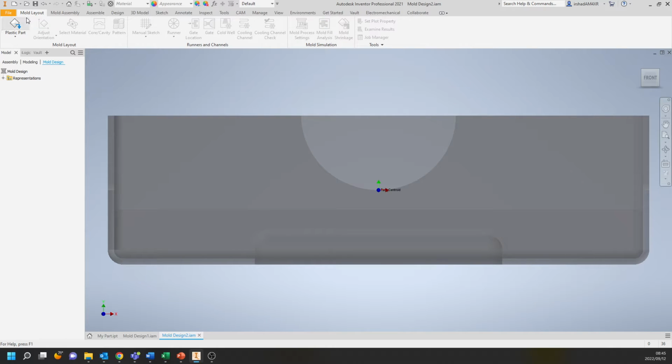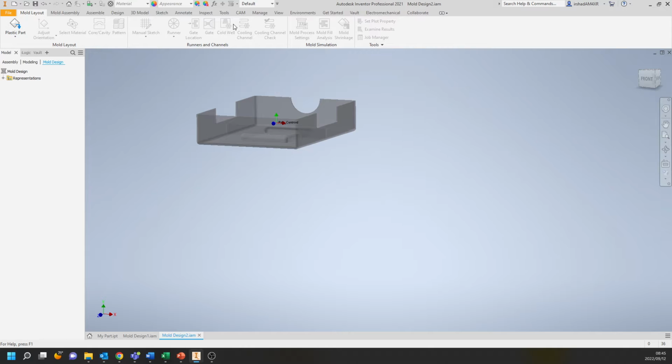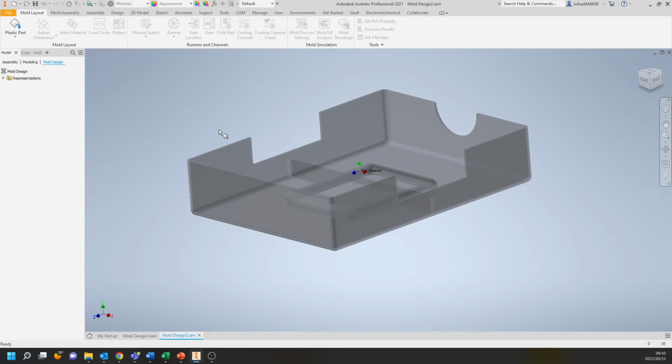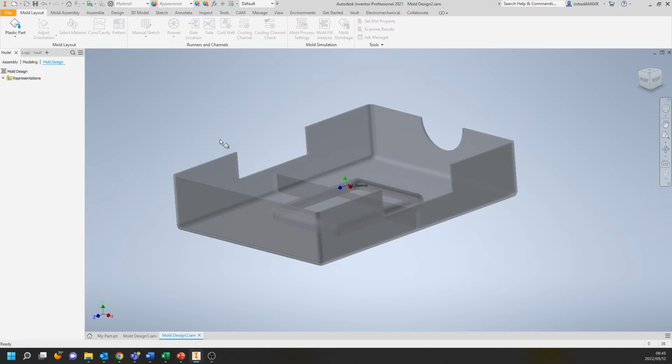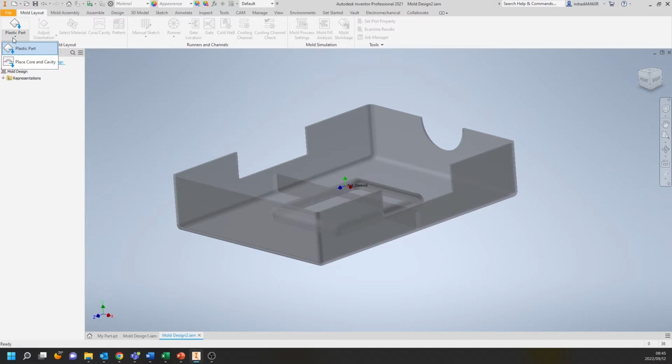You'll see up there the contextual menu, and basically everything is grayed out when you start because it's just taking you to the mold design environment, but it doesn't know yet which part you want to include or need to be made a mold for. So you'll see the only button here is either to pick a part, meaning open one from the file menu, or to click something in your graphic window.